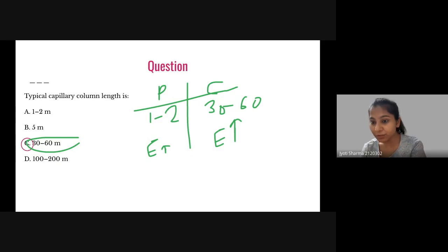The filter paper was loaded into a high volume sampler, and the ambient air sample was processed through the filter. After 8 hours of sampling at 1000 liter per minute, the filter was removed and conditioned again, and the weight was this one.